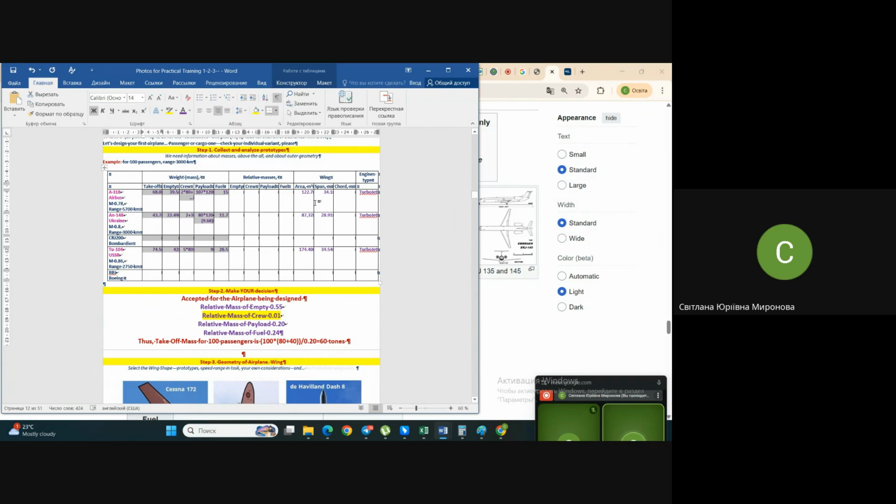And next, you also need to recalculate some additional values, like wing aspect ratio, for instance, and wing taper ratio in case it's a swept wing, not a straight one. Also, if I were you, I would do the same at least for the stabilizer and fin. Whether it's really necessary or not, you will decide.